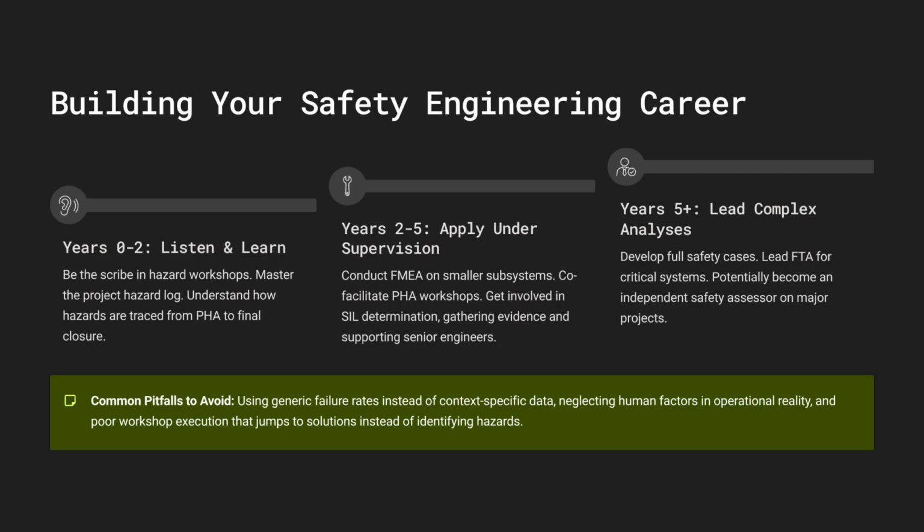But it's not just about the technical chops, is it? You mentioned soft skills being critical, especially for things like SFAIRP judgments and running those workshops. Hugely critical. Perhaps the most underrated practical skill is workshop facilitation. Leading a HAZOP or an SHA session effectively is tough. You've got diverse experts in the room, electrical, mechanical, software, operations, maintenance folks. You need to draw out their knowledge, manage disagreements, keep everyone focused, ensure all voices are heard, but prevent it descending into chaos or endless solution debates.